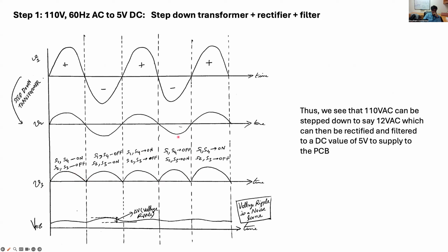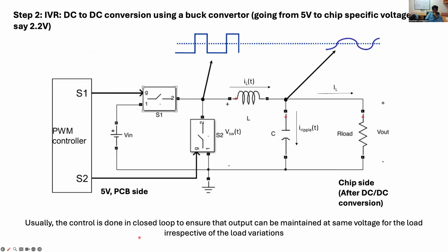And so when you pass it through the LC filter, which is basically a low pass filter, you can remove the harmonics and you end up getting approximately DC value with some voltage ripple. And by designing the filter with a certain value of inductance and capacitance for the low pass filter, you can essentially design the filter to have a certain cutoff frequency, the 3 dB cutoff frequency, so that you can control the value of ripple within a certain tolerance that you need.